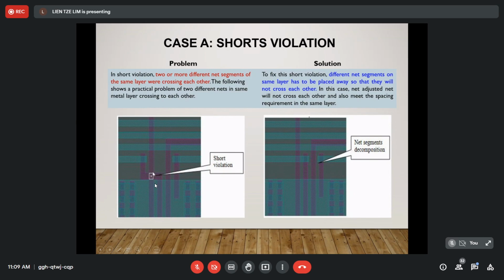If there is an overlapping or a closing here, when we perform the DRC there will be an error. This is one of the issues that arise when we perform the DRC with this design. We can solve this by removing or repositioning the layers to make them not overlap. So this is another design without the closing.